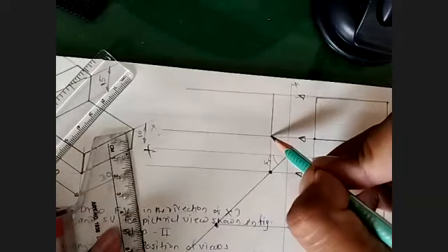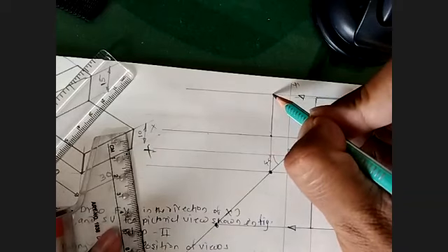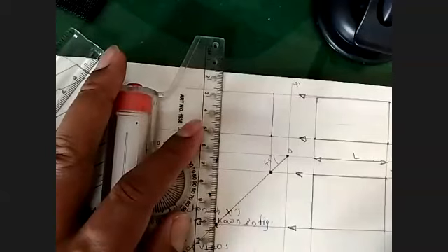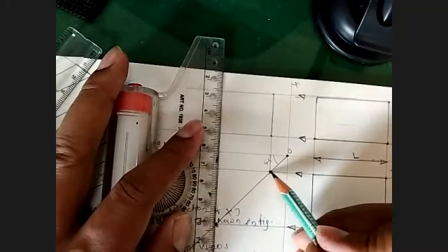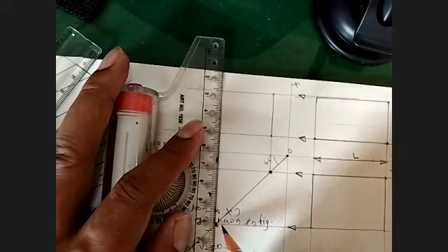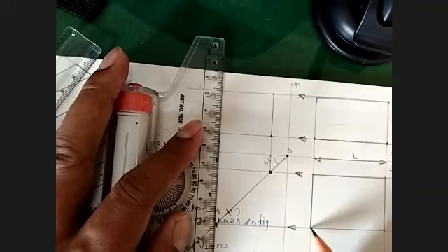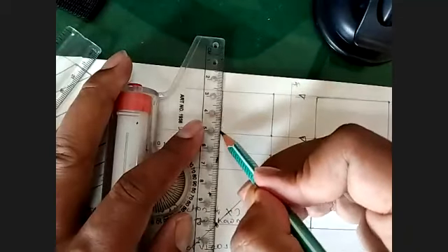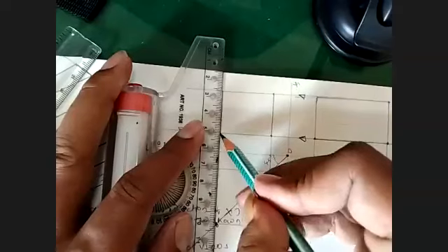So when I take it horizontal and then vertical, the distance from this to this is nothing but the height. Then I will draw one more line parallel to this from the second point. This is the first point on the 45 degree line, with reference to this. Now the extreme width point is 30 millimeter here, and that I am projecting. So further I will take this and extend it.